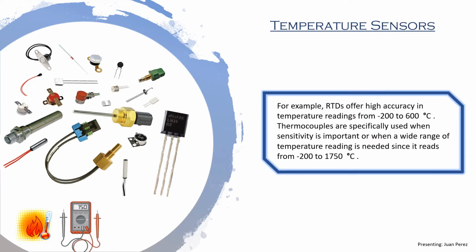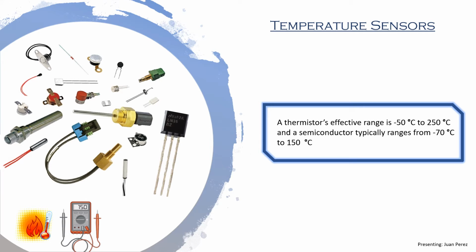For example, RTDs offer high accuracy and temperature readings from -200 to 600 degrees Celsius. Thermocouples are specifically used when sensitivity is important or when a wide range of temperature readings is needed since it reads from -200 to 1750 degrees Celsius. A thermistor's effective range is -50 degrees Celsius to 250 degrees Celsius, and a semiconductor typically ranges from -70 to 150 degrees Celsius.